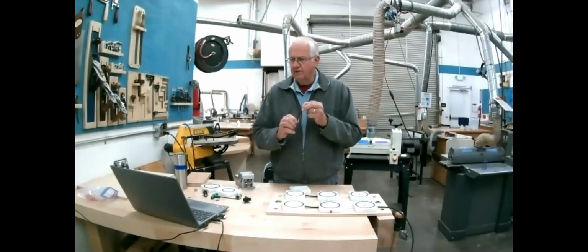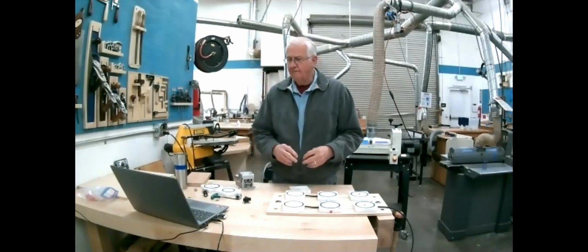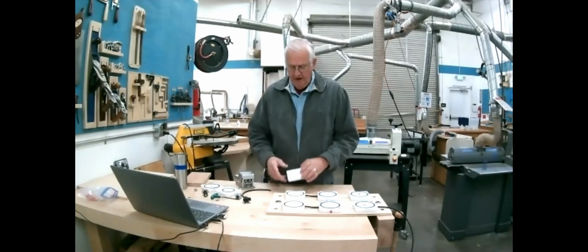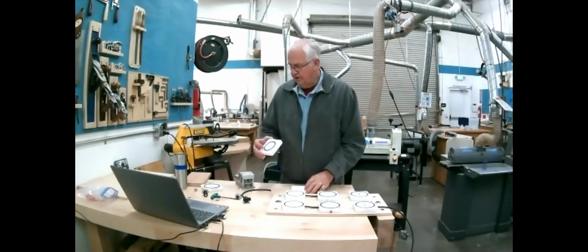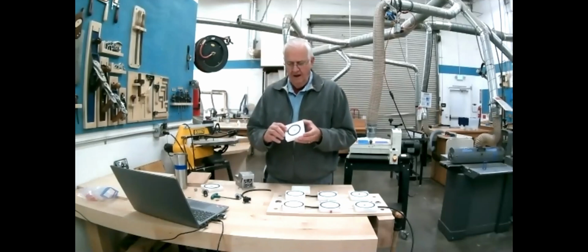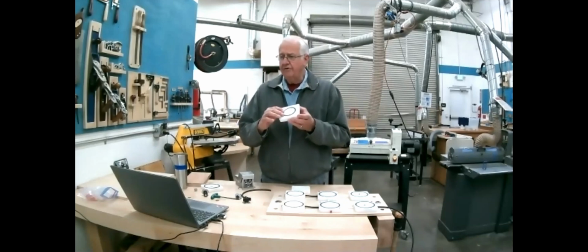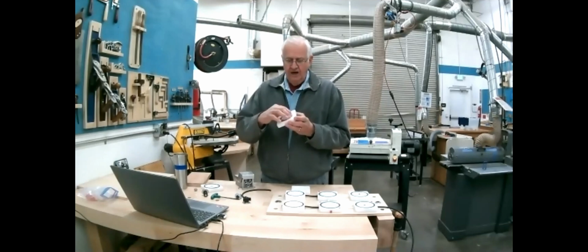So I just cut a channel that's the length of the circumference of that circle, and put the gasket in the channel. You're not going to be able to see this well, but the gasket, of course, is proud of the top of the piece. So I actually cut this channel with a 5mm end mill bit, and the gasket material is 1/4 inch, so it's a little bit wider than that.